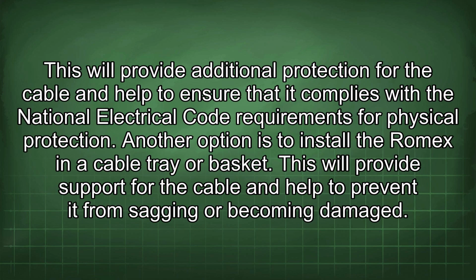This will provide additional protection for the cable and help to ensure that it complies with the National Electrical Code requirements for physical protection. Another option is to install the Romex in a cable tray or basket. This will provide support for the cable and help to prevent it from sagging or becoming damaged.